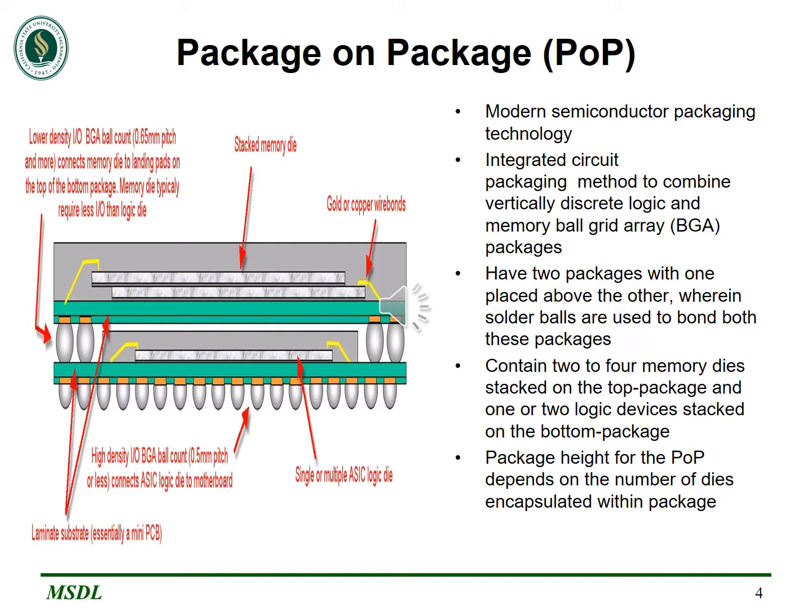This is the general architecture of package on package semiconductor, with the top package connected to the bottom package by means of grid array balls, and this structure is connected to the PCB board using the same grid array balls which are present below. The top package can stack 2 to 4 memory dies and the bottom can stack 1 or 2 logic dies.